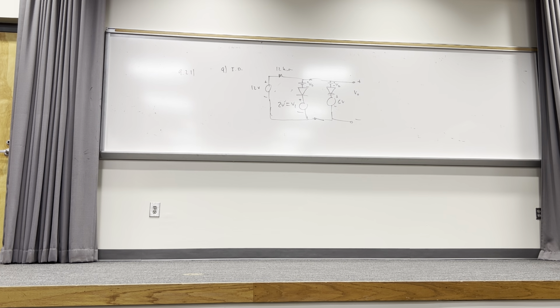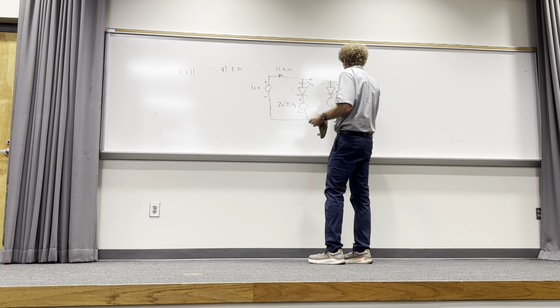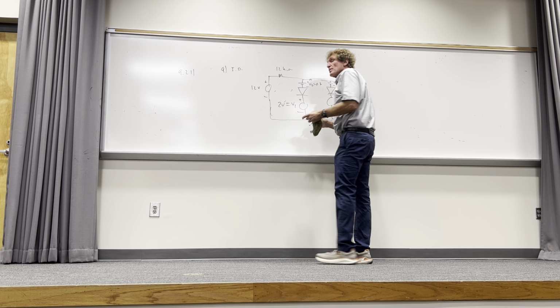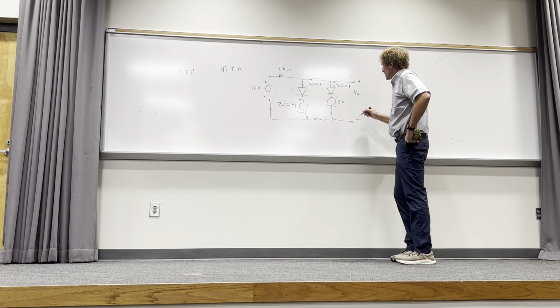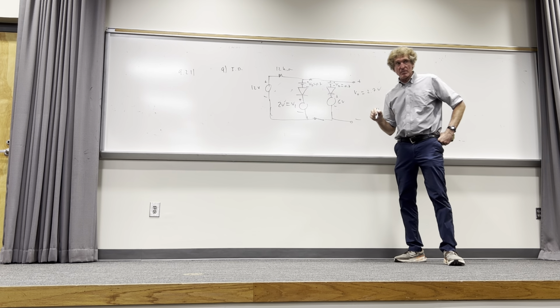Oh yeah, then he says Schottky. Don't worry about Schottky diodes, that's a special application. For 0.7 volts, if V diode is 0.7 volts in both of these, the only thing that happens is now it won't be just 2 volts, it will be 2 plus 0.7, or this would be 2.7 volts. Do you all follow me on this, class?